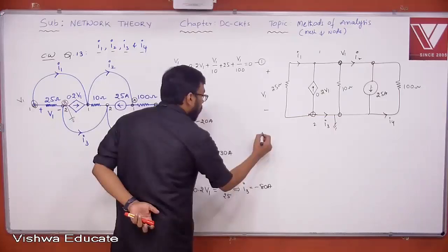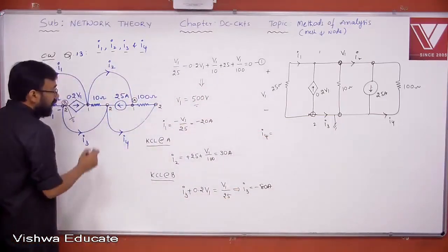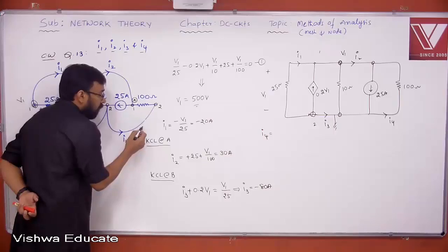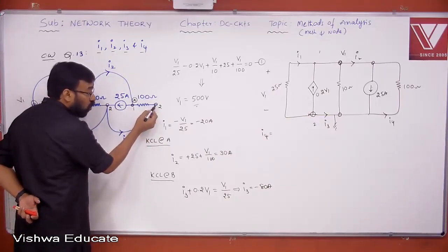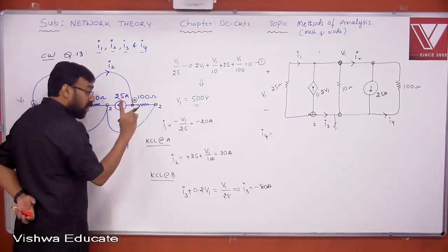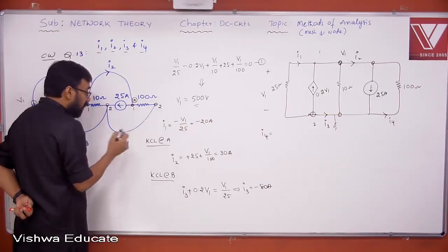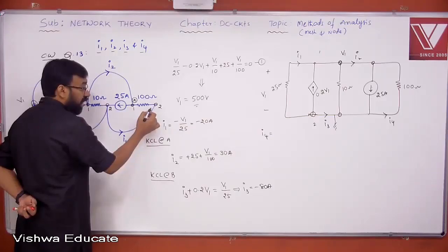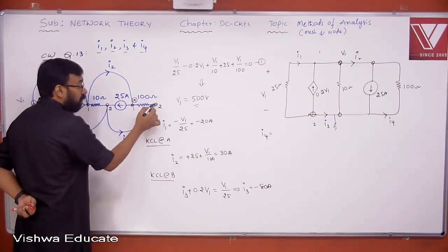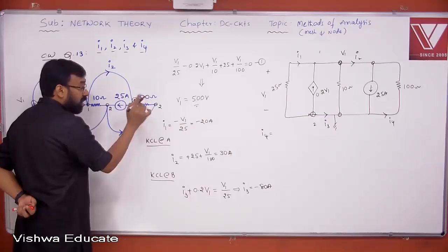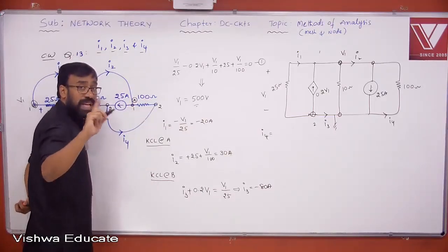Next, I4. What is that I4? Is there any resistor in this path? Understand what the degree is here. Degree 2. Wherever you have degree 2, it indicates that elements are in series. If you treat the zero resistance wire as one element, 0 ohm, and this 100 ohm, in between there is a node of degree 2. That means they are in series.